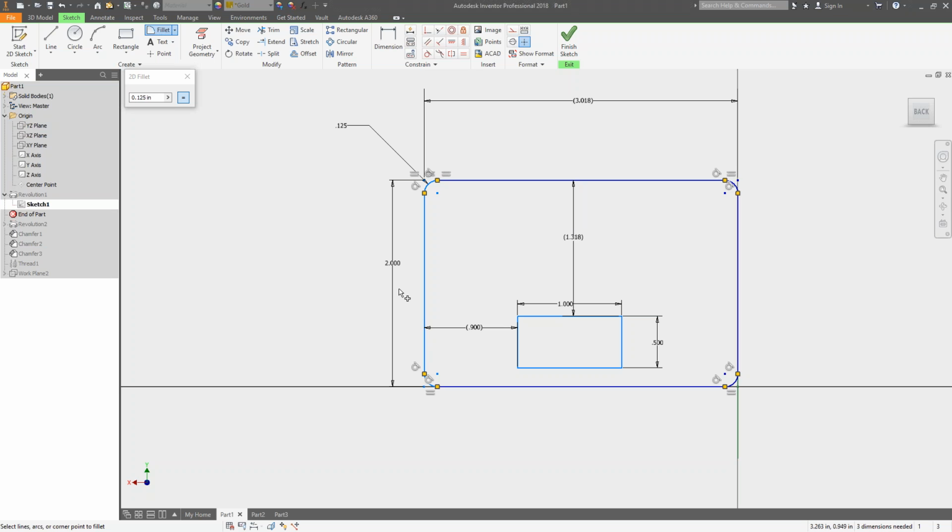And just from listening to you in the past, Luke, usually you wait to do that on the final 3D CAD geometry, just for a little more flexibility. Yeah, it gives you way more flexibility. Sometimes you have to do it here just because of whatever reason, but this would be a last resort kind of fillet. I wouldn't put fillets or chamfers, any of those small details, here. I like to do that as a 3-dimensional feature.